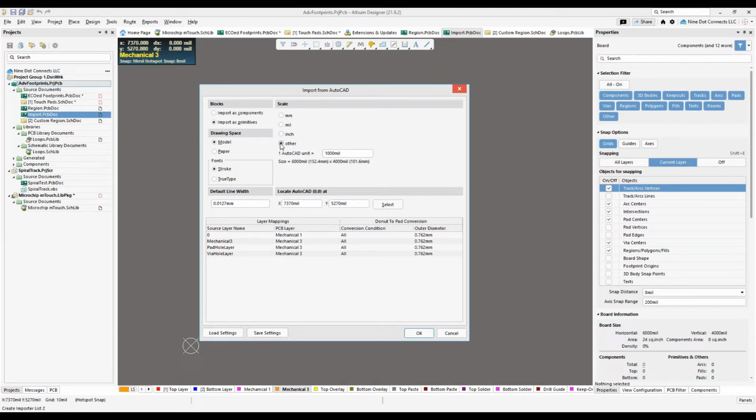If you go over here and you say, I really don't know what that size is, but I'm going to try to guess it, then I'm going to put in a unit of 10. Now, the size over here does play a role. The quadrant that we work in, the first quadrant, in fact, each of the quadrants, as far as I know, in Altium Designer are 99 inches by 99 inches. But obviously, if the socket is 24 inches, I'm probably a little too big with this, and so I'd want to possibly drop it down.